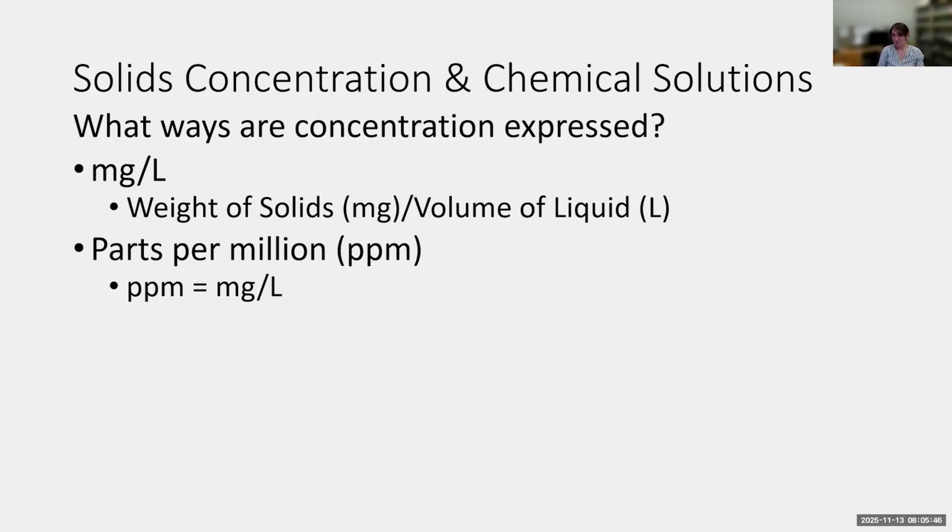Milligrams per liter can also be expressed as parts per million. So if we were to add 10 milligrams of hypochlorite salt to 1 liter of water, the concentration can be expressed as 10 milligrams per liter or 10 parts per million. They mean the same thing.